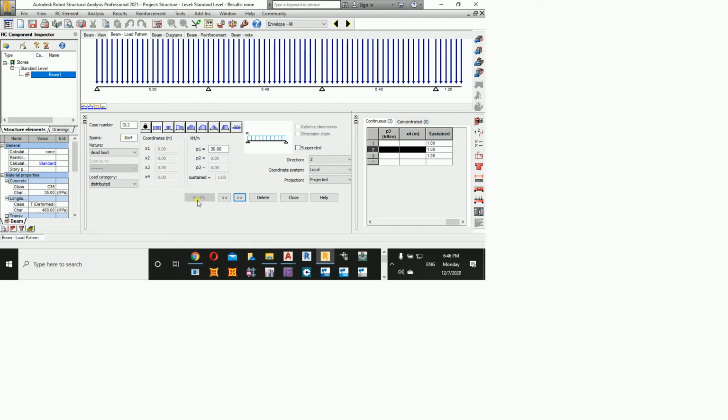Are we okay? Now, if I want to talk about the second loading, which is the live load, I can click on next. Can you see? Now it will open the live load for me, and then once again it's going to be 1, 2, 4, and then modify. Now you can see it's for all the spans. Are we okay? So if you are taking copy, it will be copied with the loading. If you are adding a span, it is without the loading, but you can add the loading here. So different options, different approaches are there. Are we okay?